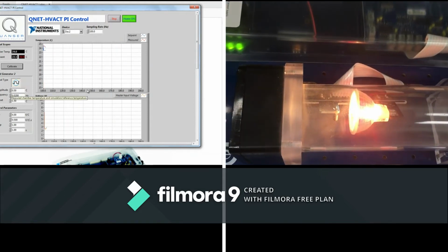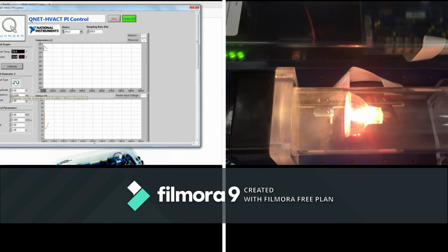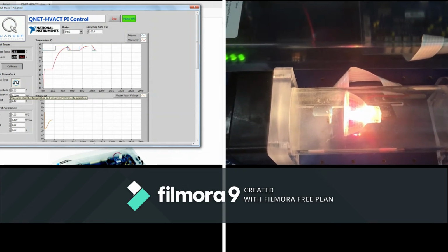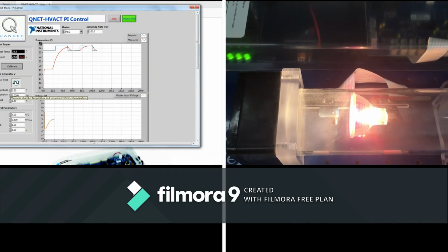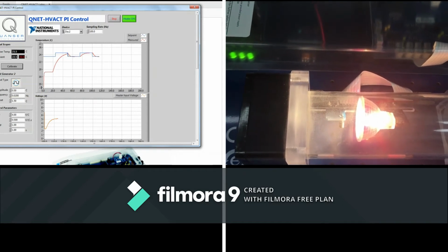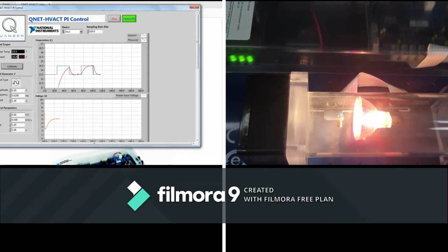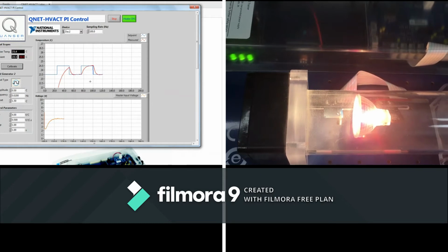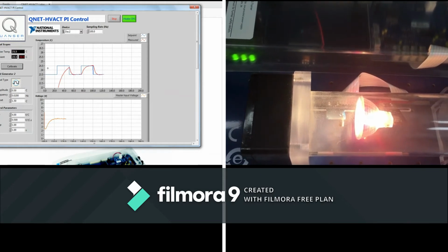Of course, we can control the time axis starting from 0. We can also control the y axis. So we will increase this to 27 and keep it starting from 22 to have a better view of our cycle. So what is the difference between these two cycles? This one is transient, so the system is heating up.